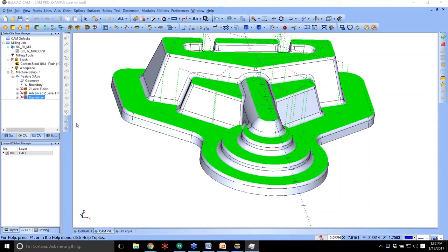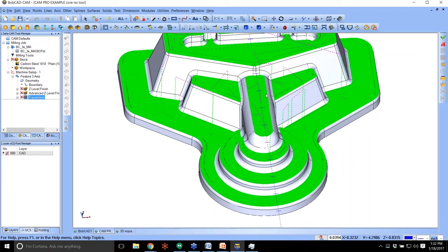Good. So if you look there, see how that toolpath is only cutting in that angle range? What's nice about it is you can turn on those options. So it's handling the flat areas, it's handling the radiuses. We can make it go to 40 degrees, go a little bit further down if we want to. It does the same here. So what it does is it analyzes the model and finds those angles. So you guys can turn on that option and use it when there's that scenario.